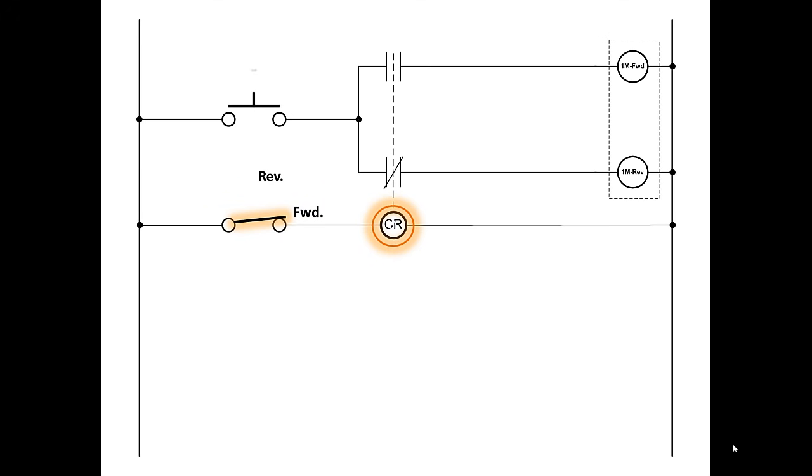So we add a momentary push button into the circuit, and the other switch, not the momentary push button, but the other switch becomes a direction selector, and the push button actually initiates the door motion. This arrangement allows us to select a direction, and for this reason we call it a selector switch.